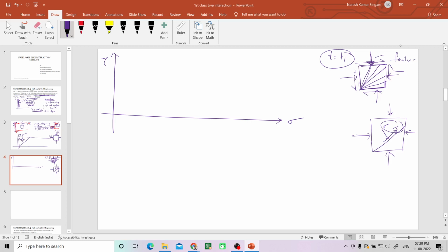So if you take all the sigma and taus, sigma 1 comma tau 1, sigma 2 comma tau 2, sigma 3 comma tau 3, like that sigma n comma tau n, take all the points and draw them in this plane. Just put those points, because sigma and tau, this is x and y. If you put all those points, you will get a circle. Of course it is a full circle, but generally it is shown as a half circle. Every point on this circle defines a combination of sigma comma tau, right? Because it is in this plane. That sigma and tau is on one plane among the infinite number of planes. This point represents one plane, this point represents one plane, like that it is the condition of the soil element.